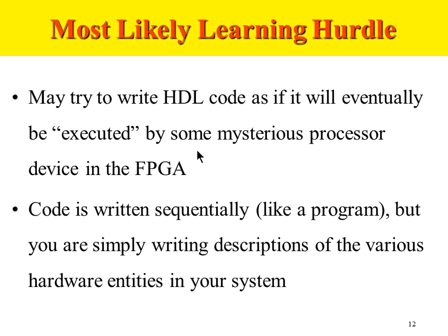That's not how HDL code works. We have seen the entire flow. We start out with Verilog code, we verify it, then we synthesize it, follow the backend process, then we generate something called a bit file. That bit file is a programming file, which is then used to program the FPGA, and the same thing goes on for ASICs. So the entire chip can be designed as per your logic. There is no inbuilt processor by default. You can have a processor, but there is nothing by default. The entire chip is programmable, or in the case of ASICs, the entire chip can be designed as per your logic. A processor may or may not be present.